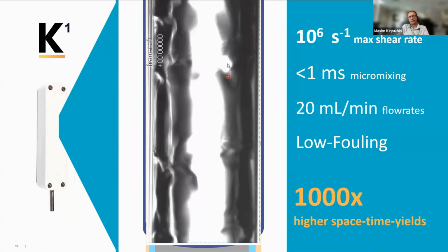Again, there could be different scenarios depending on experimental conditions. But in one most common case, we have essentially a laminar flow of liquid along the capillary tube and a turbulent flow of air in the center. This turbulent flow generates waves on the surface of the liquid. And these waves facilitate the mixing between the two liquids. This is how we can achieve very controllable mixing of the liquids, and in this way control the size and morphology of the particles formed upon the contact of these two liquids.